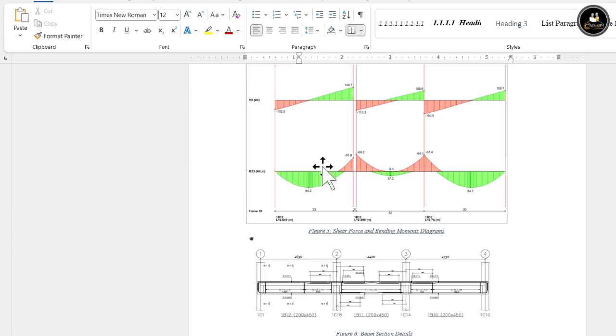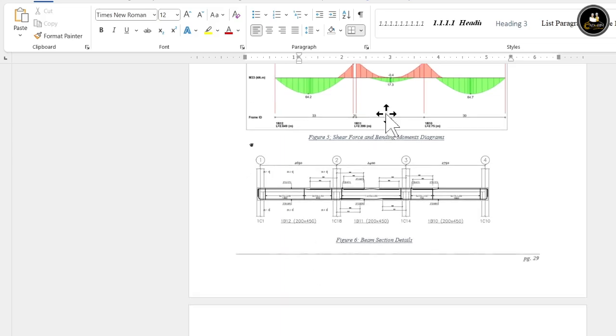So we want just to avoid the software detailing it with the top reinforcements. It will detail based on the moments. If you reduce your moment, it means that you have lesser reinforcement at this edge, and so more reinforcement can actually be redistributed to the mid span and at the top of the spans, the hoggings.